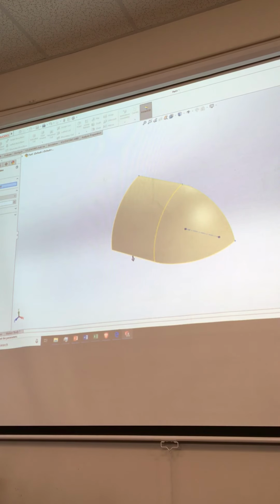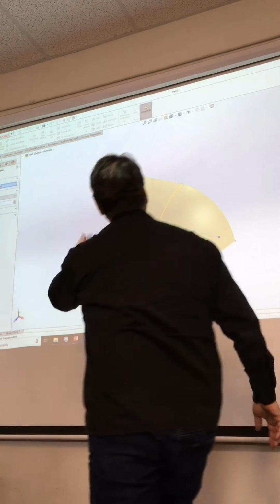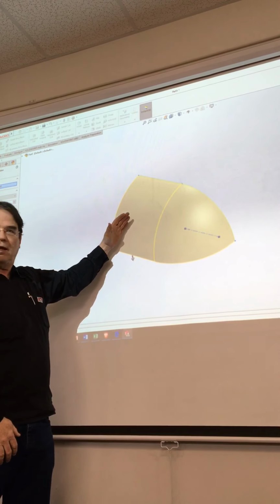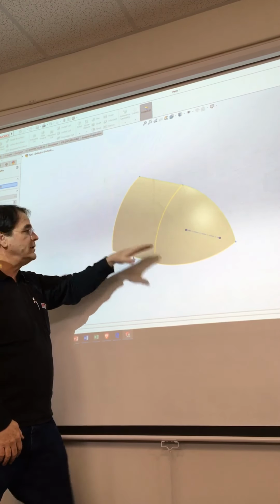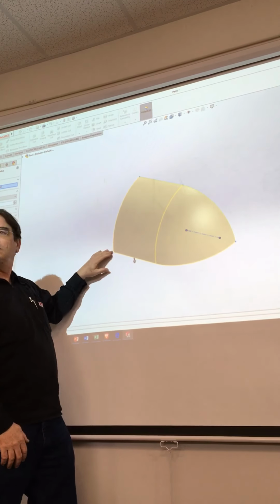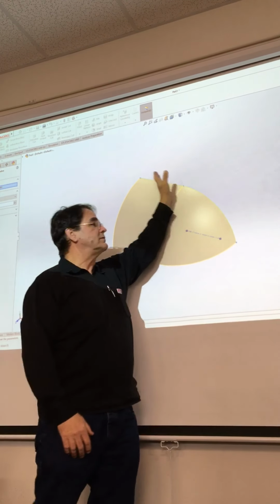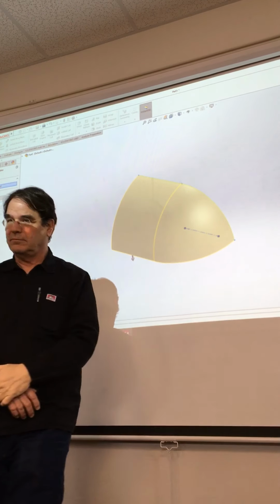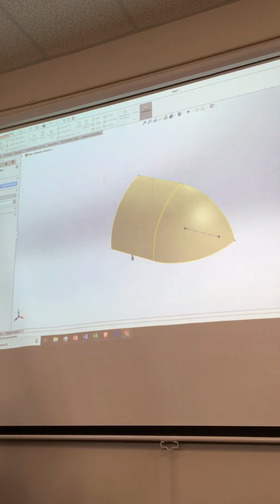So part of the process of doing it in this class is we're going to learn how to apply symmetrical boundary constraints. Because the tank is symmetrical about any of these. It's symmetrical about this line over here, because I only modeled half of it, right? And it's symmetrical about this plane over here, and it's symmetrical about this plane over there. Right. Okay, are we buying that?